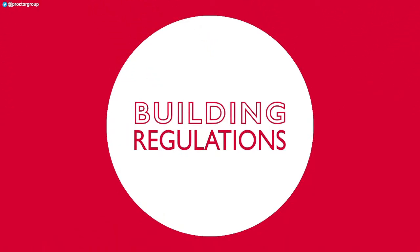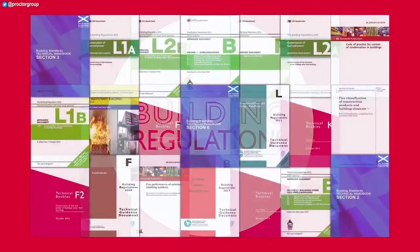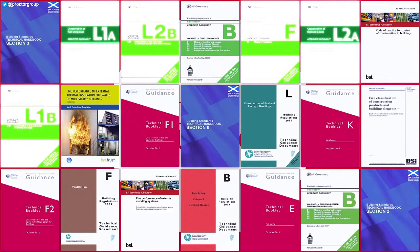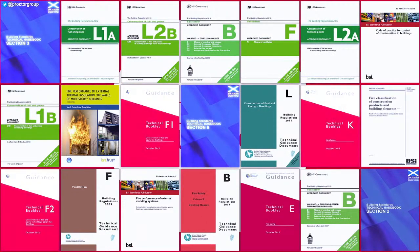Building regulations. As with any type of construction, the basis of good design in modular construction comes from a good understanding of the building regulations themselves. Today, we'll be focusing mainly on the documents relating to energy performance and condensation control. So that would be Approved Documents L and F in England and Wales, Technical Standards 3 and 6 in Scotland, Technical Booklets K and F in Northern Ireland, and Guidance Documents L and F in the Republic of Ireland.